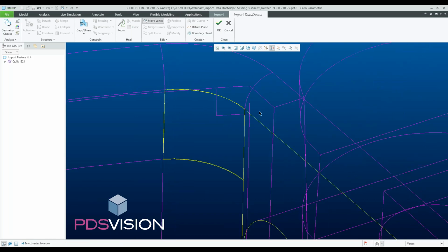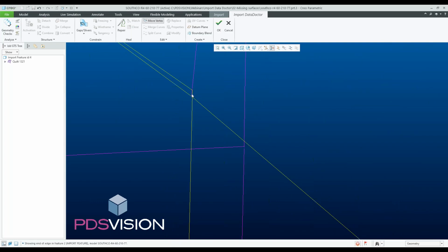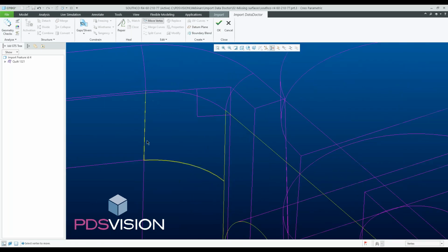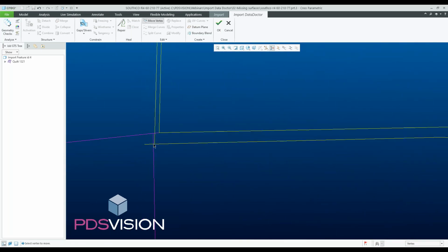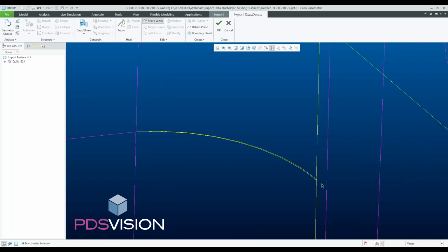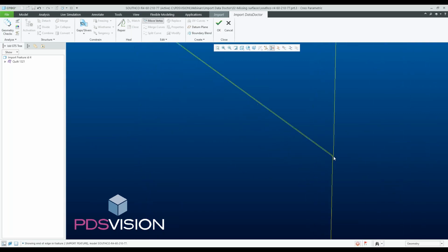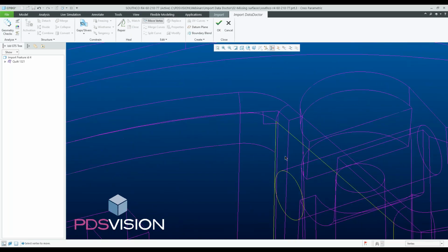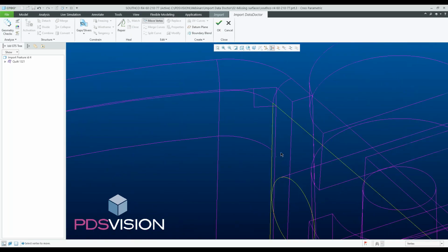As you see, nothing happened yet. But we take the next corner, we're being very close here. And as you see, Creo merged the edge. We will do it on the other one. We will be close. We are lucky today, and we merge this one. And as you see, it's not quite where, but he decided to put it there. You don't have 100% control on this.